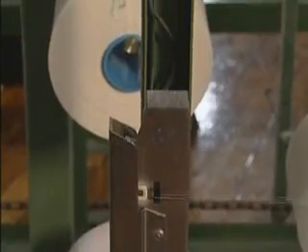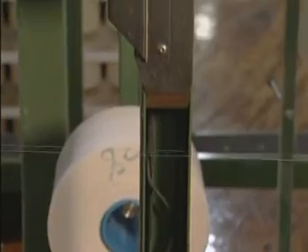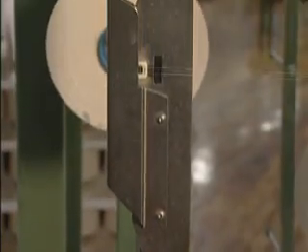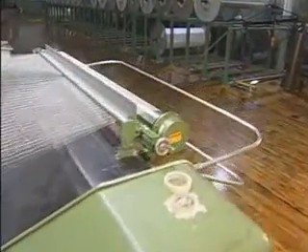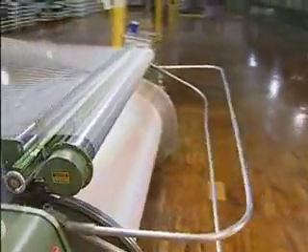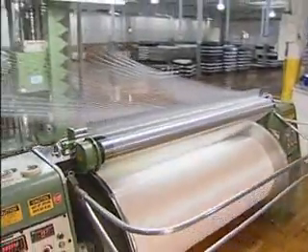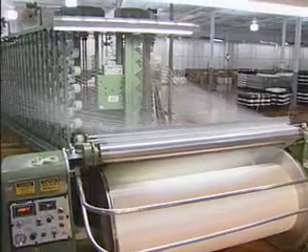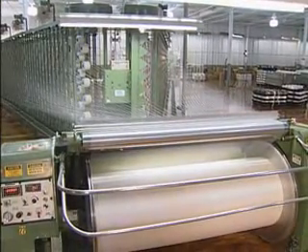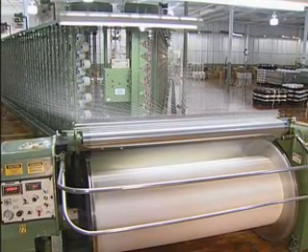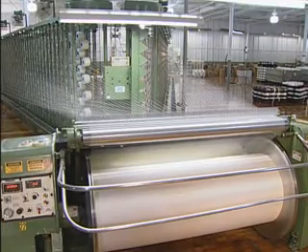The path the yarn follows on the creel is through tension devices and stop motions. Next, the yarn passes through a reed or comb that guarantees even spacing and a yarn sheet width that matches the width of the section beam. In some cases, the section beam is perforated for yarn beam dyeing.